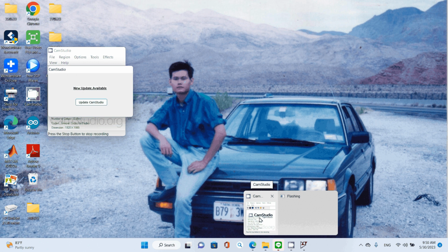Okay, let's start again to do the plot. You go to run, and you have the plot, and you add to your plot the current flowing through the resistor R1, and then you want to change this one to be positive. You simply put the negative sign before IR1, and now you want to do the cursor.